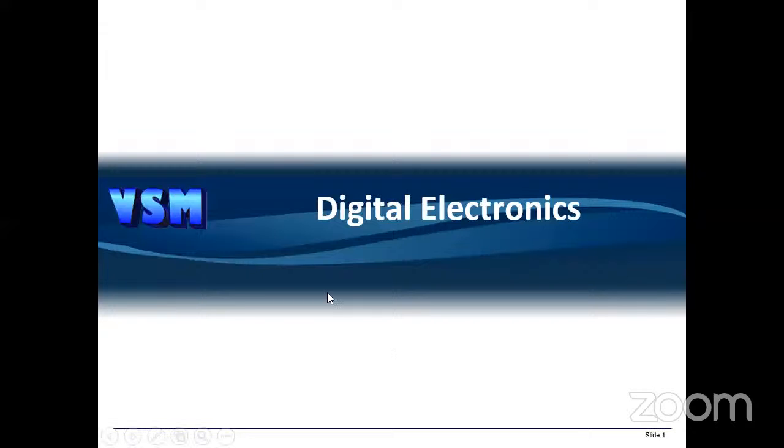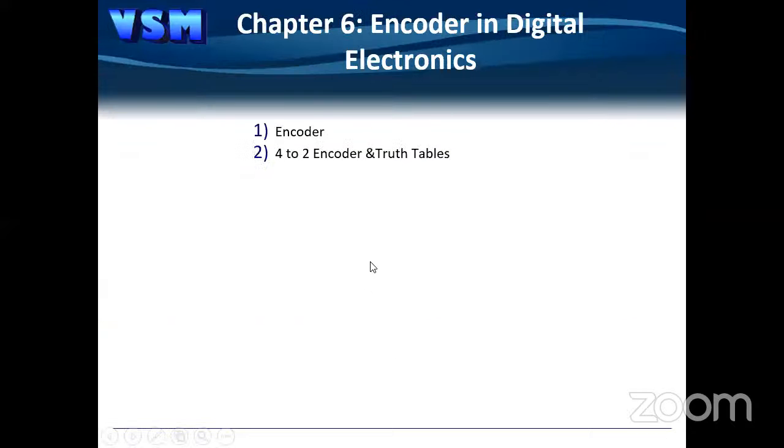Okay. Now I'm sharing my PPT, encoder. Now we are discussing encoder. Encoder is totally reverse to the decoder. In a decoder, you give n input lines, then accordingly you get 2 power n output lines. In an encoder, we give 2 power n input lines, and we get n output lines. This is the encoder.